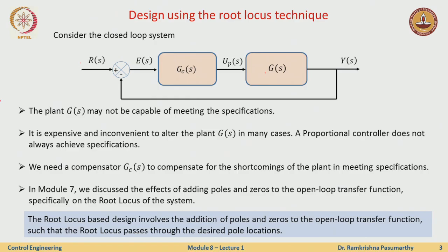Okay, so when I say I am adding a compensator, it essentially means that I will have a system with possibly some gain, some zeros, and some poles, and so on. Again, I will make sure that the number of poles is greater than or equal to the number of zeros to maintain the causality condition.